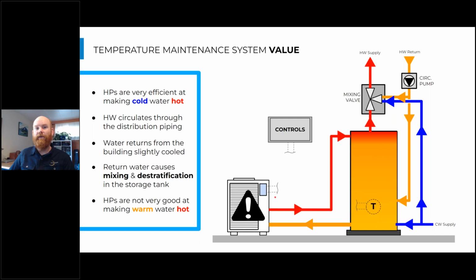It also causes issues with the heat pump water heating cycle, because that single pass heat pump water heater might be pulling in 70-degree water, and then over time it's trying to put heat into already partially heated water. So if we assume this water is 110, it's trying to take heat out of the air and put that heat into 110-degree water, which is an operating point that's typically on the boundary of the heat pump cycle.